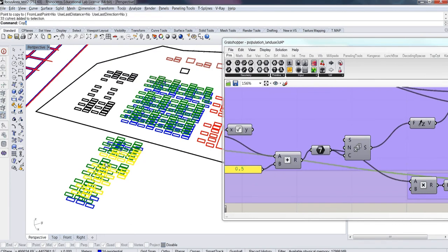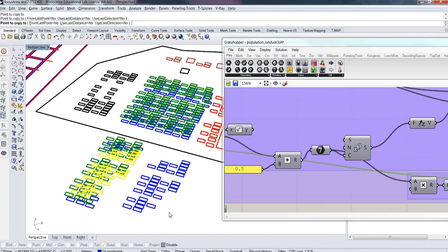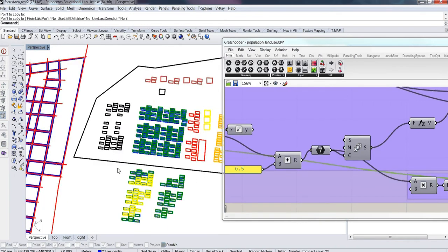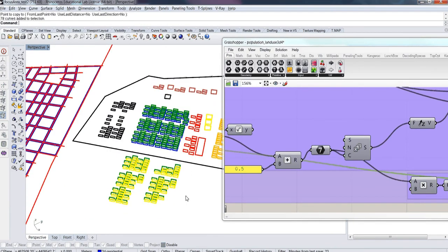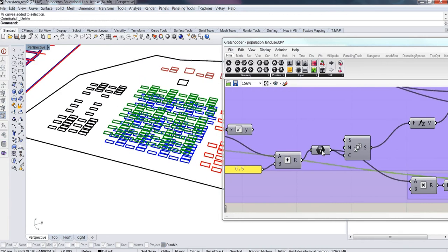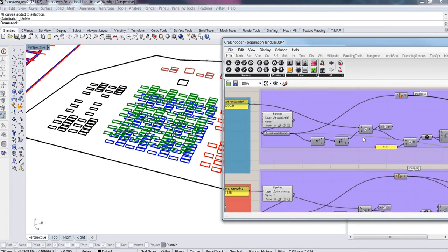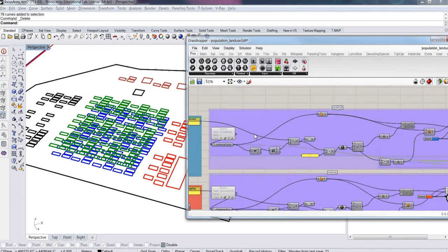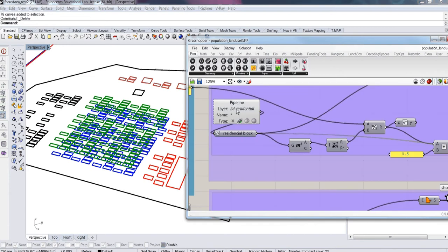See here, if I make another copy of this polylines under finish, then it automatically changes the floor level from 15 to 12. Again, I can easily select geometries and then delete. Then you see the calculation will move the stories back to 21. It's automatic. It's super useful. All right, so this is how you can load the geometry with Grasshopper layer name.